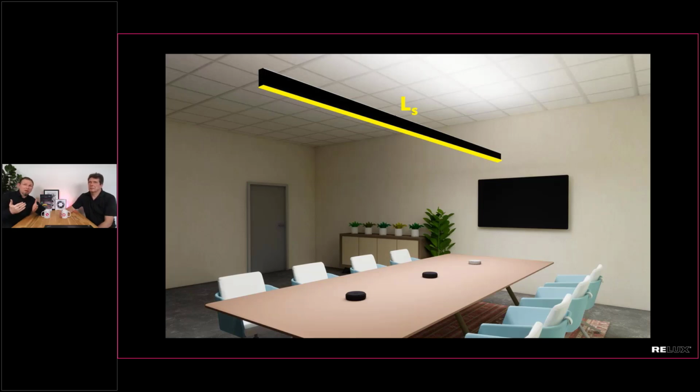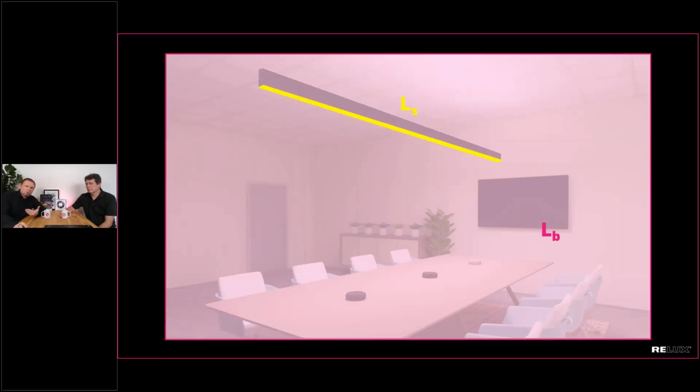And again, the size of this area has an impact on it. And also, of course, the intensity, so how much luminous flux you have in different directions. So this is the one part which is glary in a way. The second part, in contrast to this, is the background luminance. And the background luminance is also, as you can imagine, hard to calculate. It's not easy, and there's a lot of interpretation of what really goes into this background luminance.